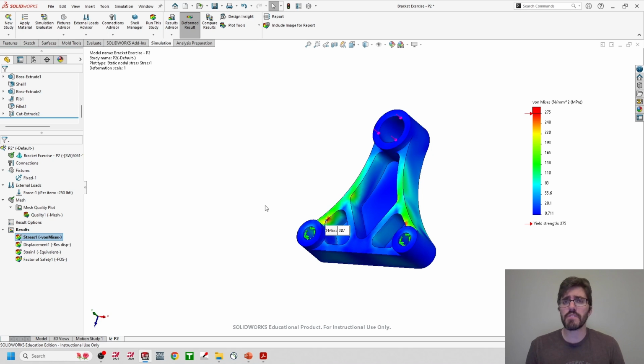And what's really nice about this whole method and this workflow that I was just showing you is you probably were thinking about it as we were running this, but you didn't have to set everything up again because you did that save as. You basically made a copy of everything that we finished in P1 and you moved into P2, and now you have all the same criteria, all the same settings. You didn't have to update the edit definition of this table, and we're all good to go. You just have to go and add your geometry and then mesh and run.